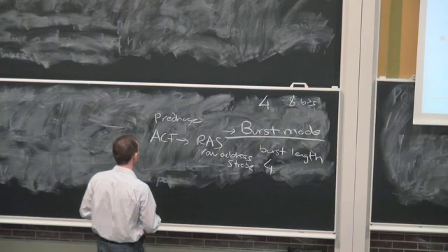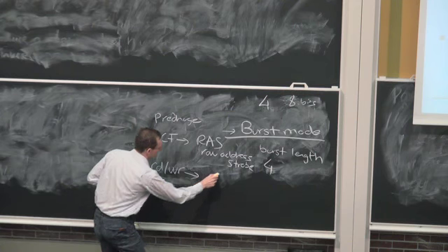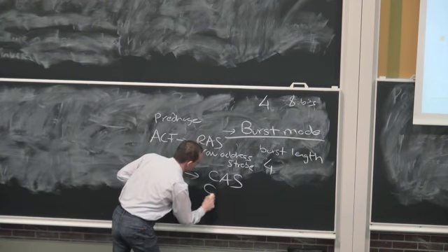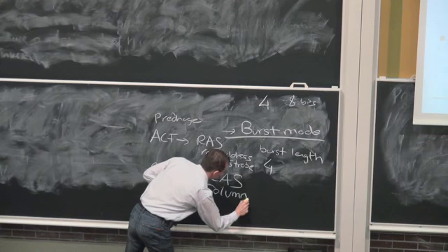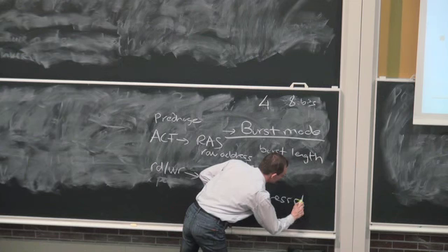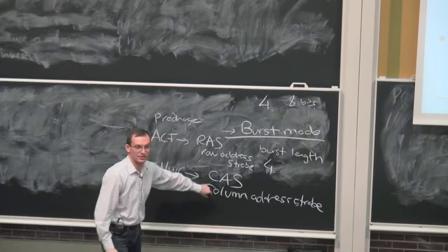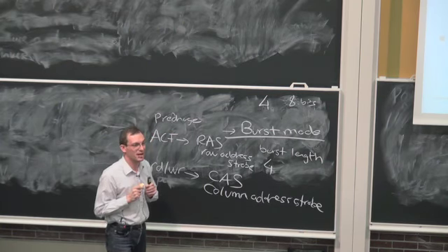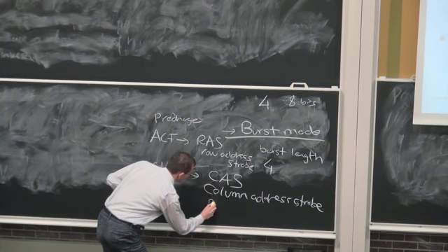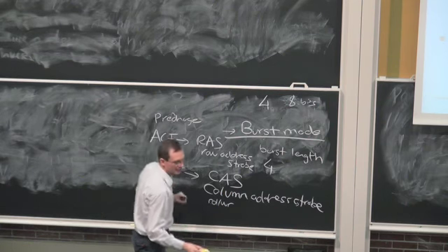That's the row address strobe. Read or write commands to a column are also called CAS, column address strobe. Basically, you're providing the column address and telling the chip to mux out the column from the row. Also, you need to provide a read-write bit, if you think of the read-write command as a column address strobe.